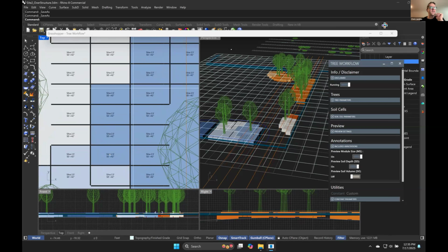For each cell, it shows what the soil depth was there. I think this depth is actually calculated from the very top grade, which is something I'm just noticing, from the very top grade down to excavation. So it doesn't include that space in between. That's one reason it's doing that. We've brought this excavation level really low here for this example.